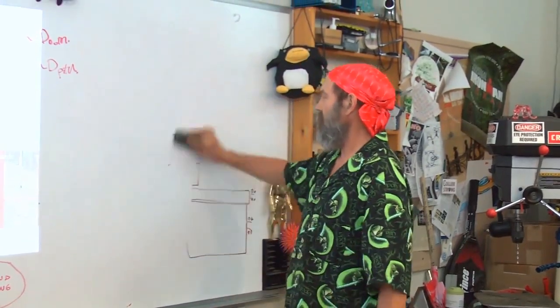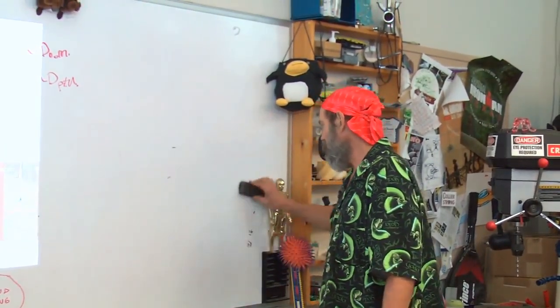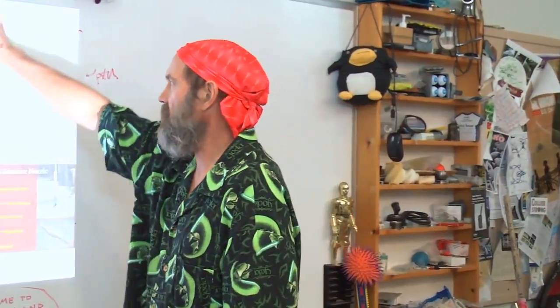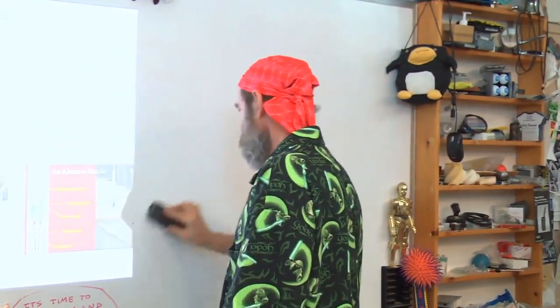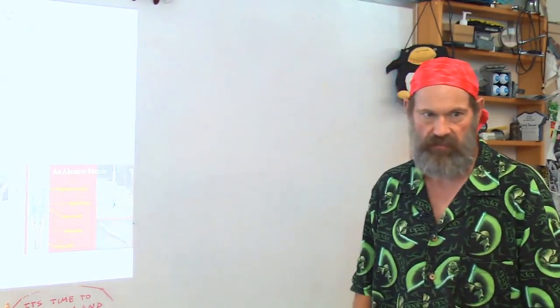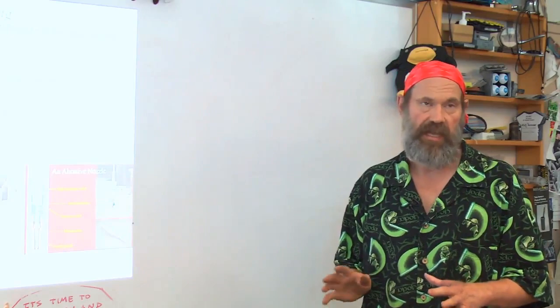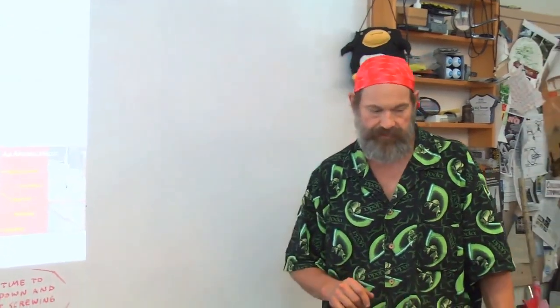Also beware that many of the 3D printed plastics don't last real long with time. So you may make some gears from them and they work and they look good, but it's not something you necessarily want to rely on for your product working for a long time, because some of the plastics tend to age not very gracefully.